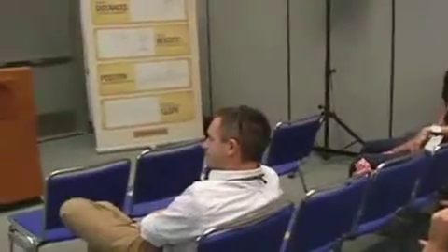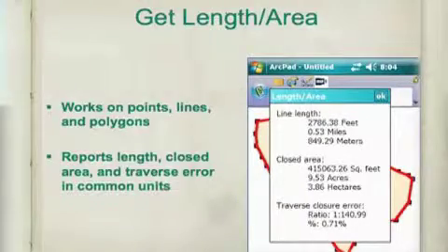If we're doing 3D mapping or a 3D point, we have the ability to adjust the target height. For example, you go to set your shot, your guy with the target calls out, hey, it's 2.8 feet. You try and shoot, you just can't get it, too much foliage in the way, so they move it up, and these things might change shot to shot, so you still have this kind of last chance to adjust the target height. And again, if you have auto measurements on, you won't ever see this. The measurements will just come directly in.